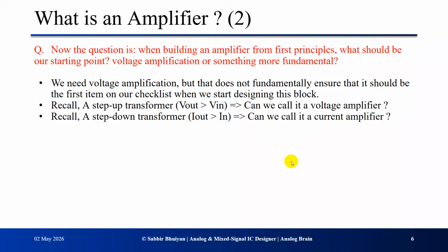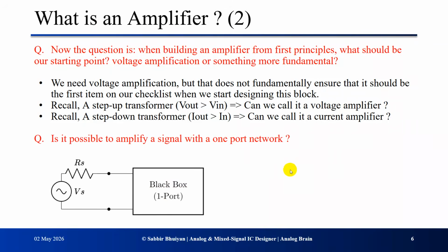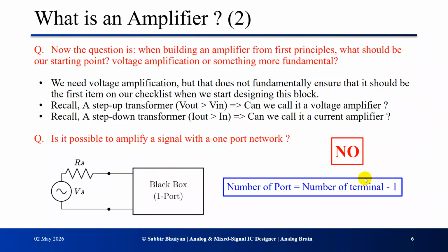Now, here's the next question. Is it possible to amplify a signal with a one port network? Okay. The answer is no, and let me show you exactly why. A port is defined as a terminal pair where current enters one terminal and exits the other. So the number of ports equals the number of terminals minus 1. With only one port, your input and output share the same terminal. There is no separation.